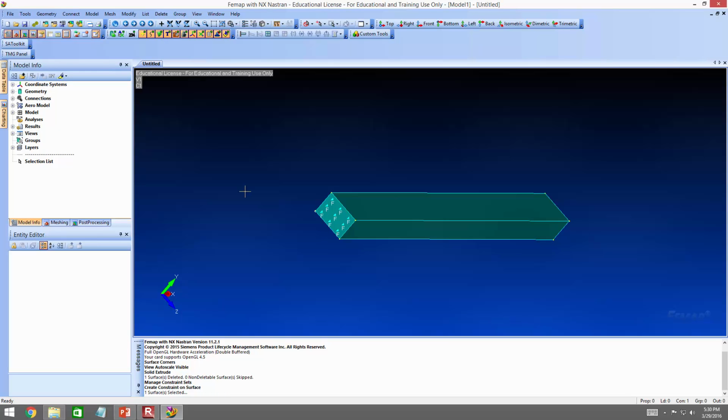All right, so let's say you applied boundary conditions in too many spots. I'm not saying you screwed up. But one thing to point out, and let me show you all this on the screen, that's what this model tree is for. So watch this. I'm going to go into Model. Click that down there, and now we see a number of things. We see elements, materials, properties, loads, constraints. You should see a drop-down list associated with constraints. So what you can do is go down that. There's that first set that I created. And then here's my constraint right here, that fixed support. Go in and delete it and start over.